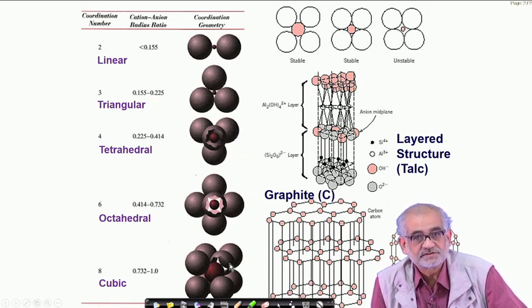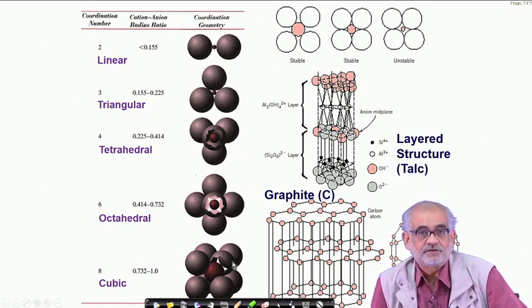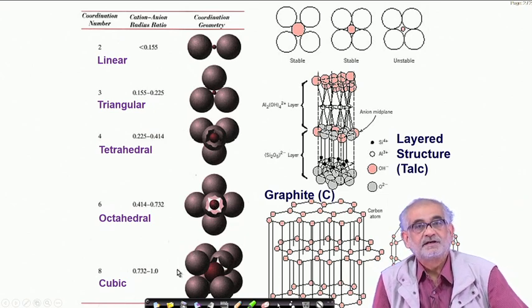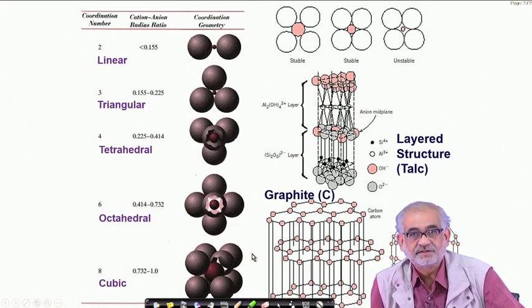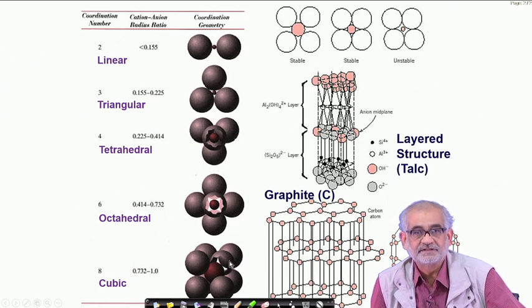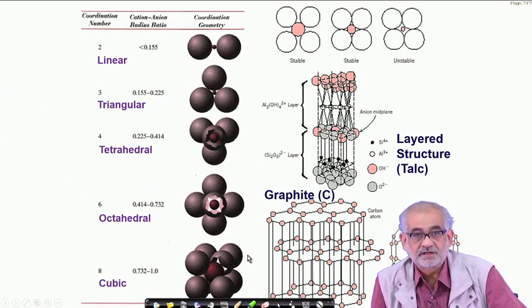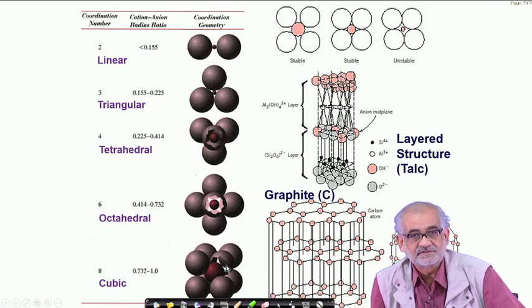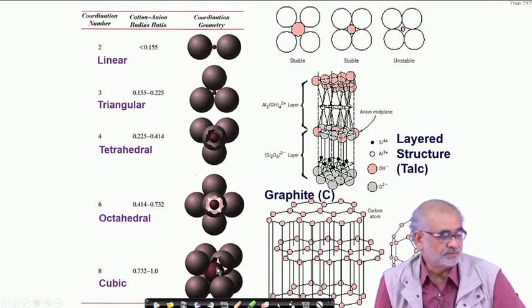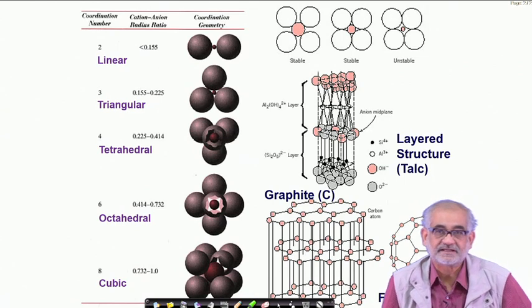The most efficient packings, which I already mentioned, are face-centered cubic and hexagonal close packed. They are possible only when you have similar sizes, so only for elemental crystals of a single species size, where the ratio is 1, and only in that situation can we have the largest packing density.